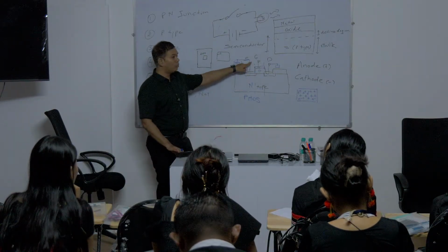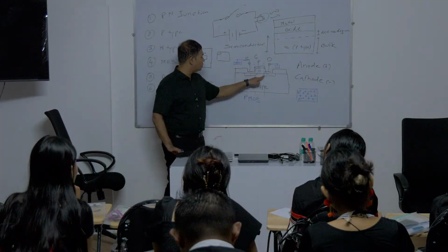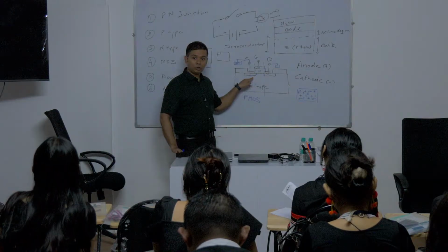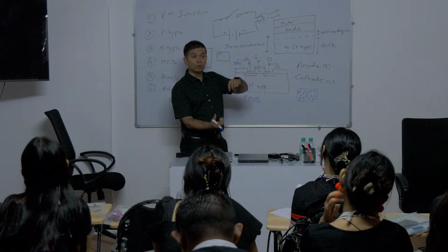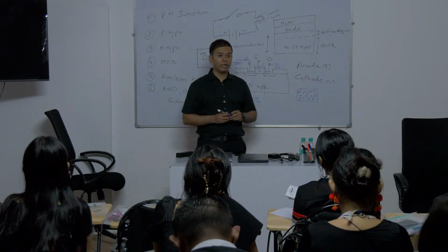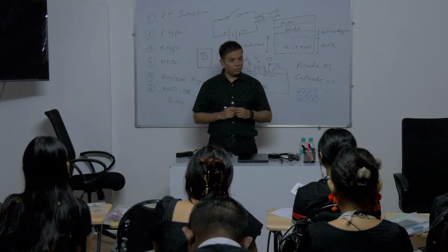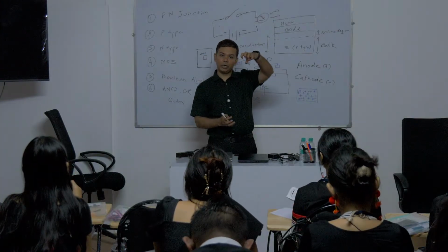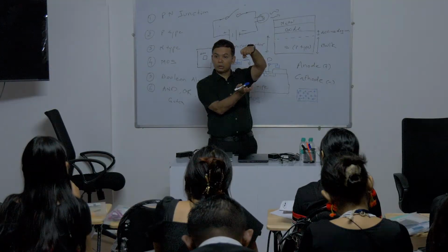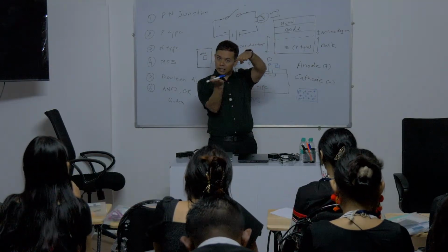Now what kind of voltage should we give so that the holes get accumulated in this region? We want our holes to be attracted near this channel region. Negative voltage, right? When we give negative voltage, the holes will come and accumulate in this region, and the negative voltage is going to hold it. So now the channel is there.